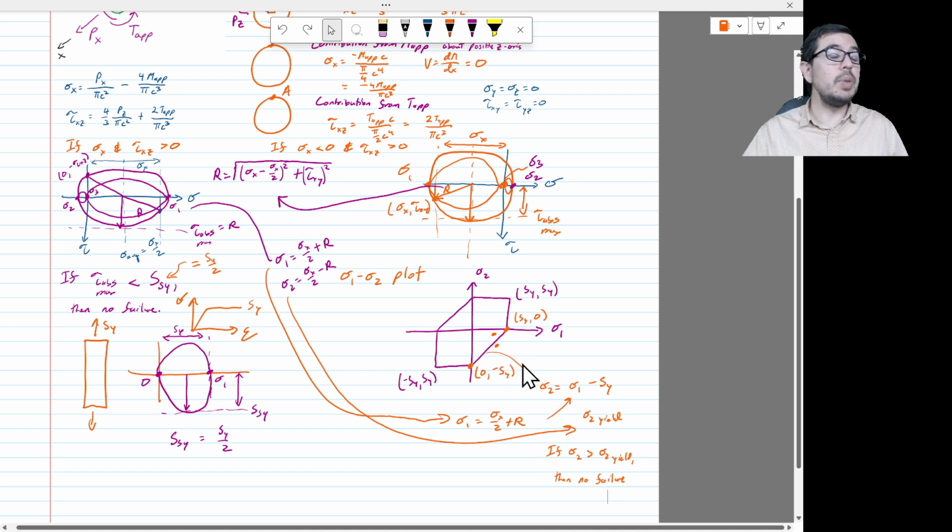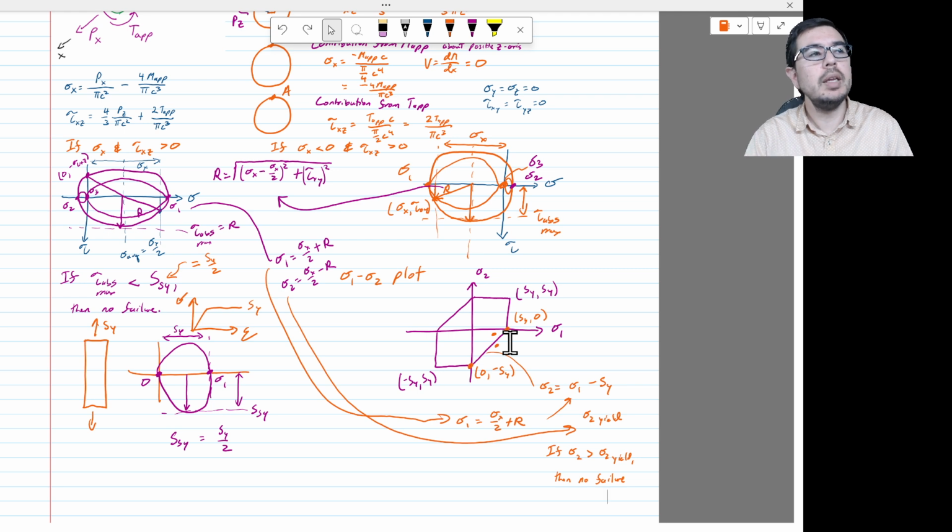And in a little bit, we'll be talking about how to also calculate what's called a safety factor. If you were to increase the load, how much would you have to multiply that load in order to induce failure? That's how you calculate your margin, your budget, your buffer for safety. And that's the safety factor.